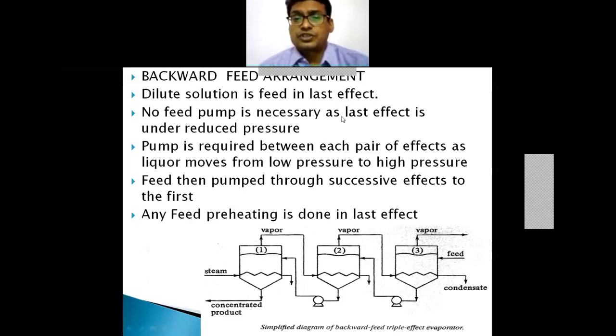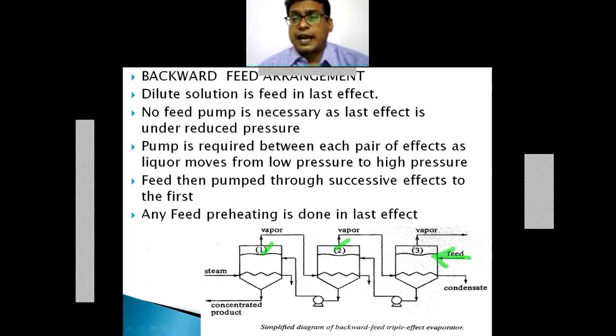This is the first, second, and third effect evaporator. So the feed enters the last effect. No pump is necessary in the last effect, because it is under vacuum, so the fluid can easily flow.